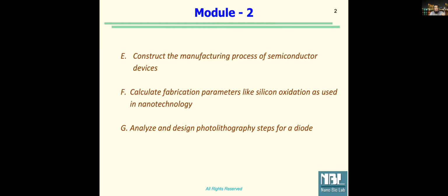Number two, the oxide is very different in electrical properties than silicon. Silicon can be easily made conductive by introducing known species like aluminum or boron, a process we call doping. But silicon dioxide is a very good insulator.